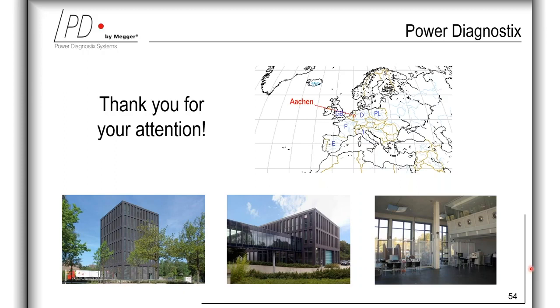So the partial discharge measurement method is one method to find defects in insulation materials or to find weak areas in insulation materials. But there are also many other defects in electrical equipment that can be found by other methods, for instance, by dielectric measurements using the other Megger instruments available. PD measurement technique has the advantage that it's a non-intrusive measurement method, and it gives an early pre-warning before it comes to a full breakdown of the insulation system.